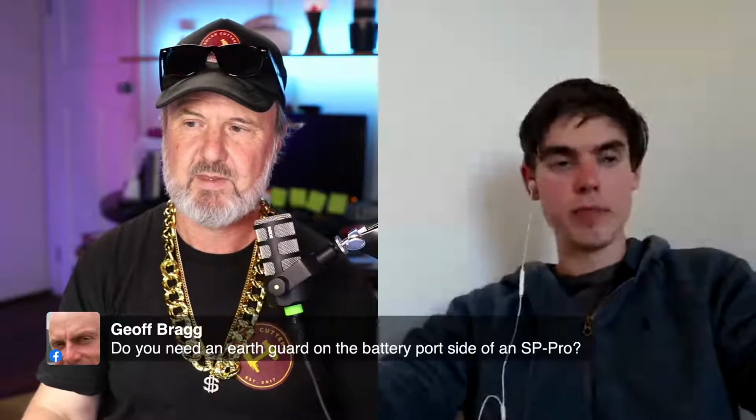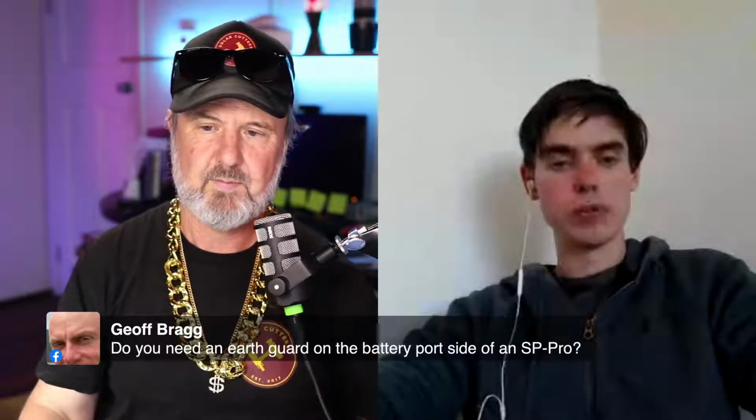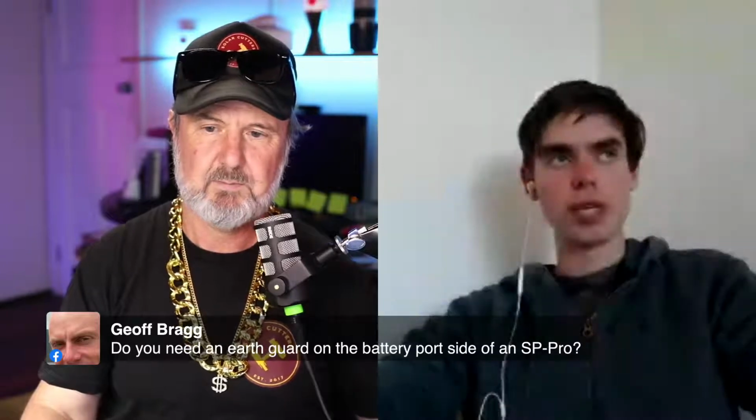Yes. So pretty much a 48 volt SP Pro that's AC coupled. The PV inverters generally take care of the earth fault detection on the PV side, and because the SP Pro is galvanically isolated, it's not required on the battery side. But Selectronic make a 120 volt inverter as well, and it is required on that unit because it is above 60 volts.